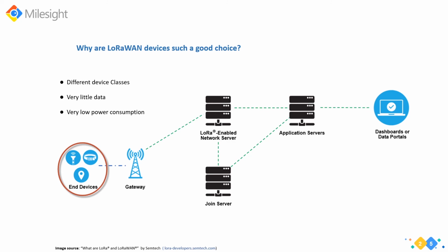Well, you can also choose the suitable spreading factor and data rate, and you can mix and match whatever you need. That versatility and flexibility make LoRaWAN really a good choice for solution providers. And you can mix different brands of LoRaWAN end devices in a solution. They can work simultaneously.